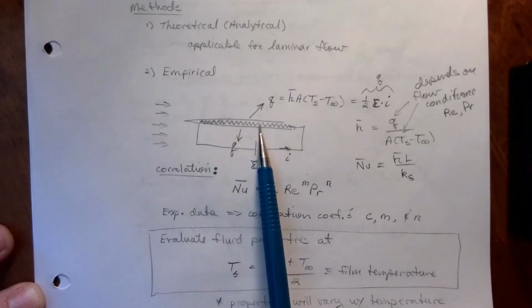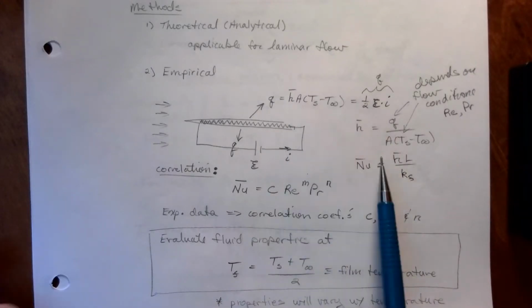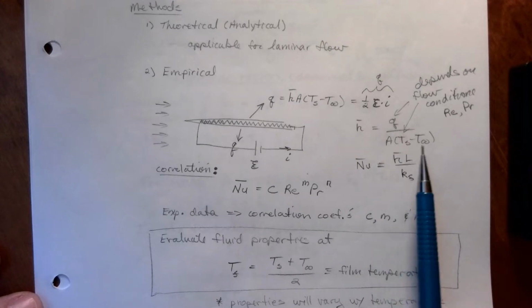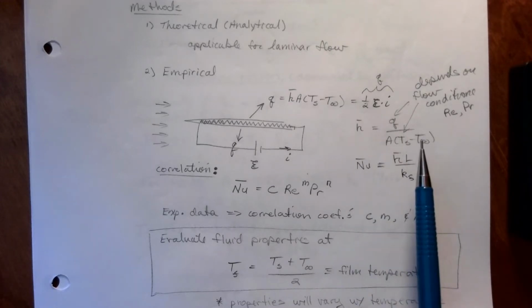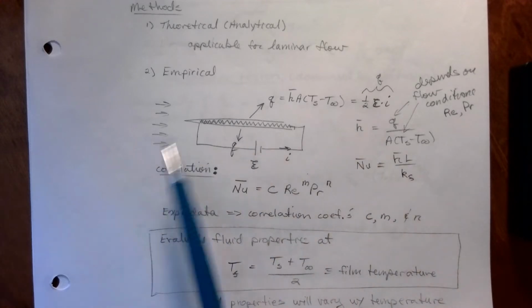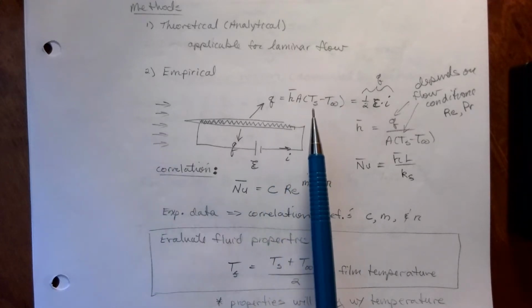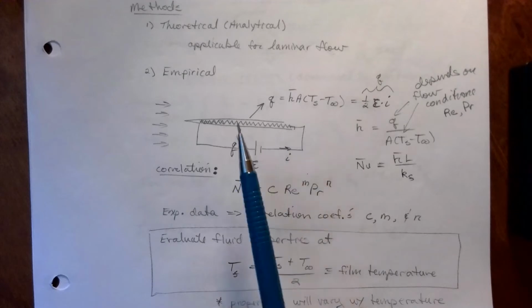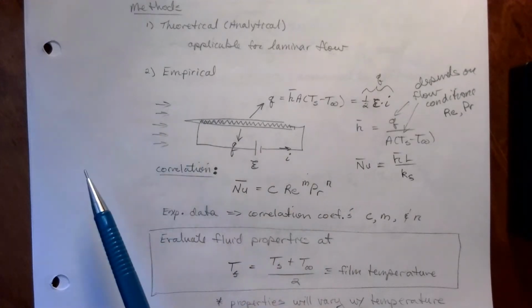So that gives us a direct measurement for the heat. Half of it goes to the top, half of it goes to the bottom. Right, so we can now solve this equation for h. This gives us a nice easy means to calculate h with some quick little experiments. Of course, then to investigate, we would increase the upstream flow to figure out a new h. Maybe change the temperature of the surface, get a new h. So there's many things that you can vary here. Put a different fluid, maybe water versus air flowing over that.